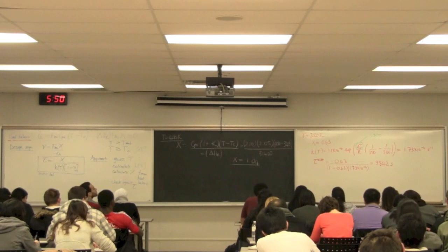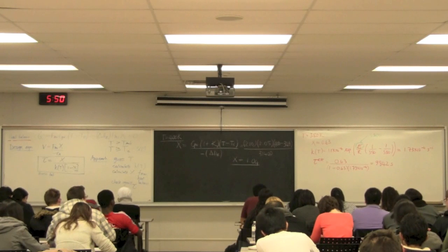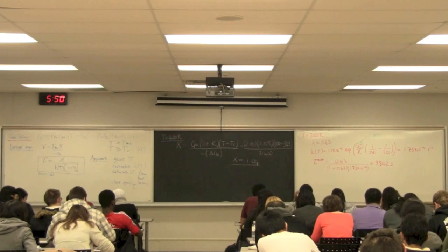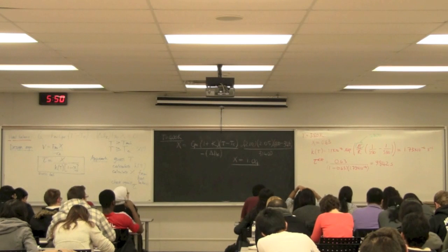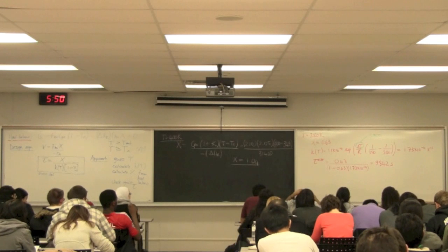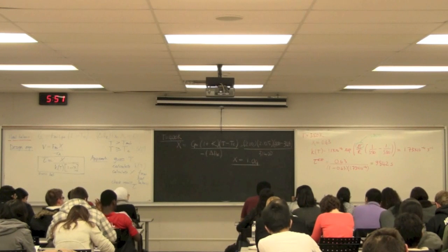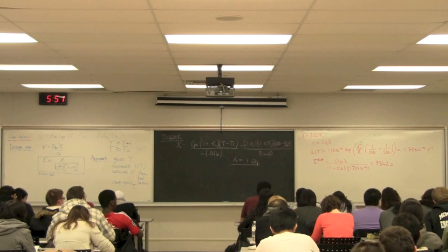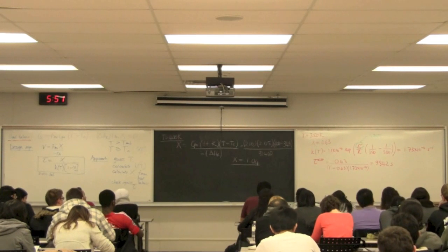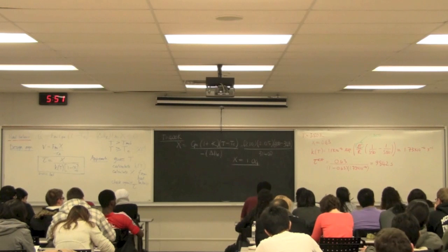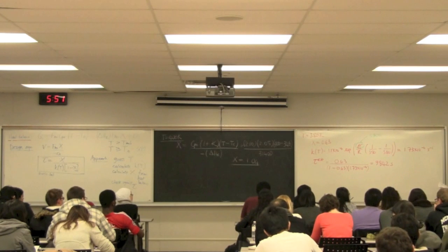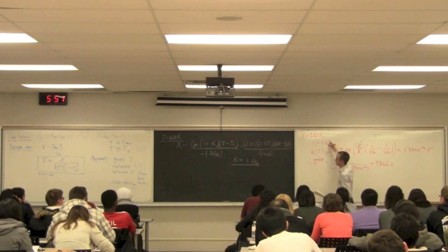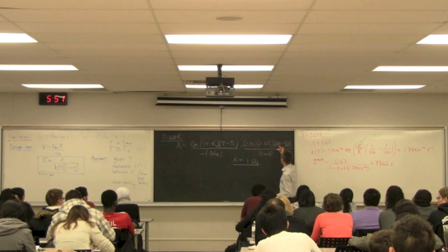Okay, so at this temperature of 380 Kelvin, I've estimated a residence time that's longer than my actual residence time. Should I go up or down? What do we expect for a CSTR? Longer residence times do what to the conversion? Okay, so longer residence times give higher conversions. So we've got a long residence time. If we want to decrease this residence time to 6,000, that means we want our conversion to be lower. What do we need to do to our conversion to get this number lower?